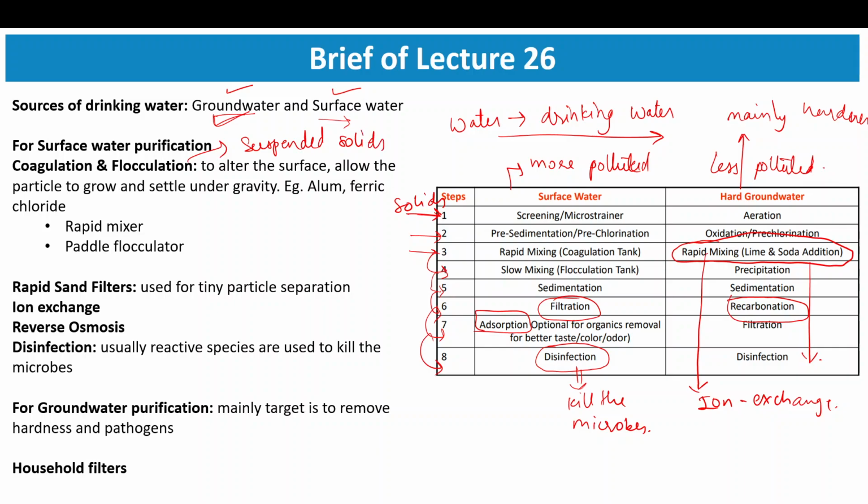So in the case of suspended solids, they will not be easily separated from water by using any strainer or any screen. In that case, coagulation is a method. Say, for example, if this is the particle, and majorly they are negatively charged.